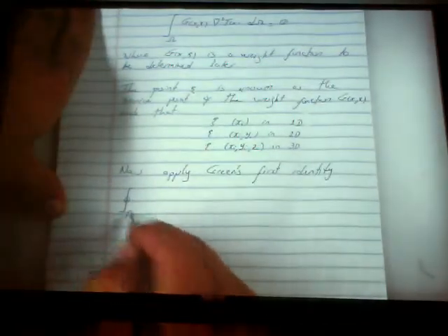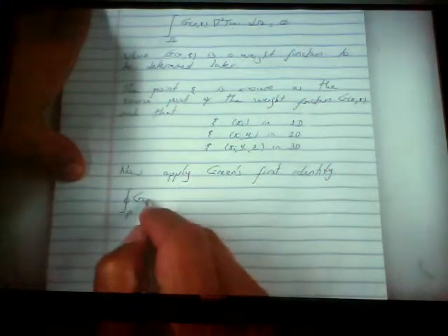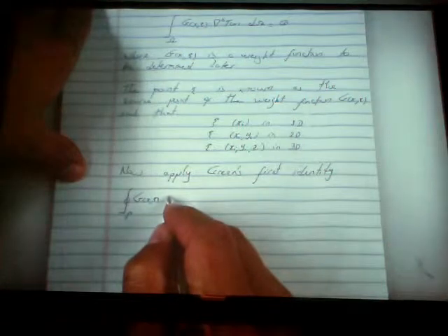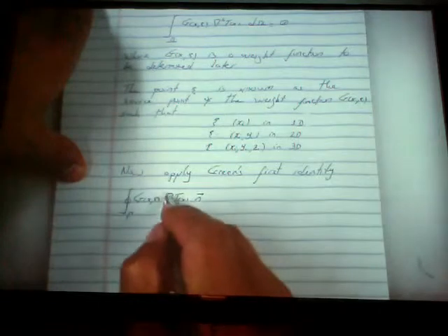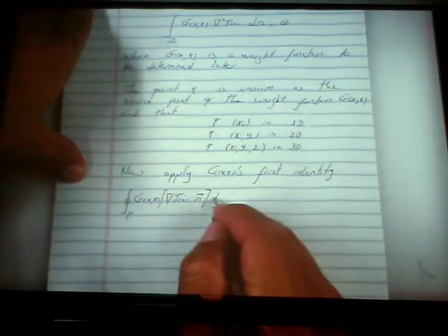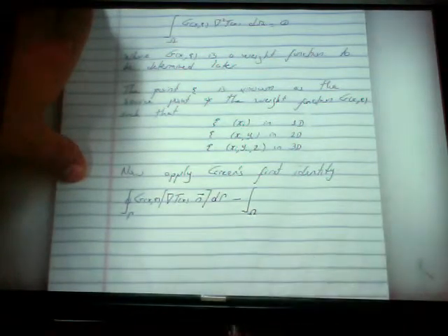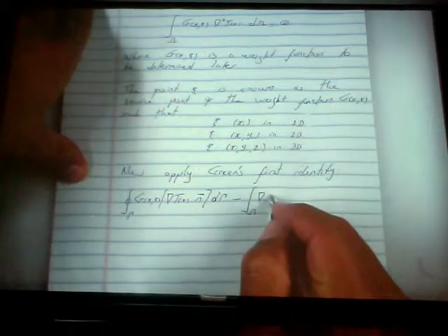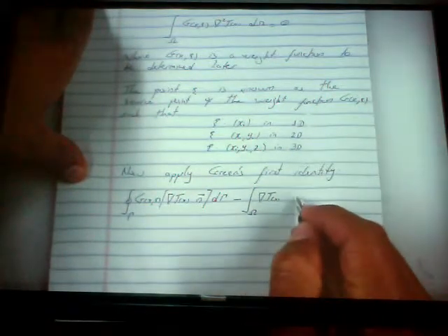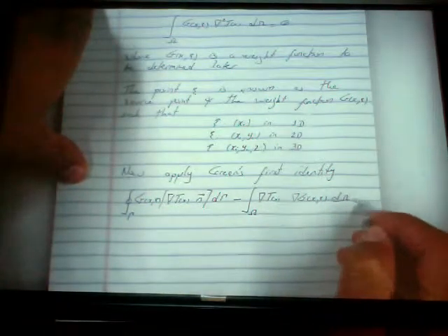Well, that will turn into an integral over the boundary of G times grad of T times the normal vector. I'm going to put this in a bracket, minus the integral over the domain of grad T dotted into grad G, d omega, and that's equal to 0.